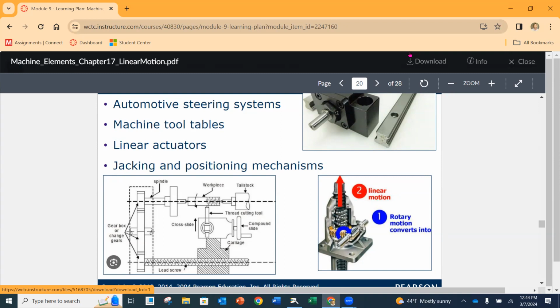So the time to make the part becomes less and less, the more efficient your machine gets. Right. So the faster you could go using ball screws, which was the preferred method, then would increase your capacity, your production on a machine tool, whether that was traversing in between before you were cutting and in the cutting speeds as well.